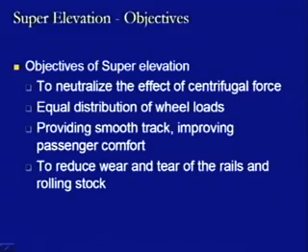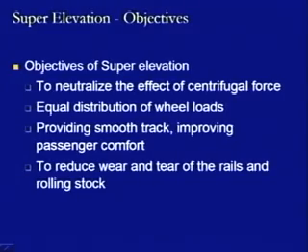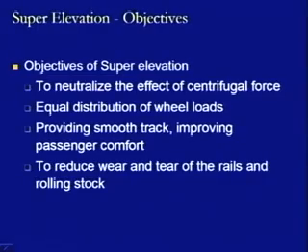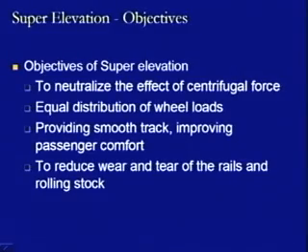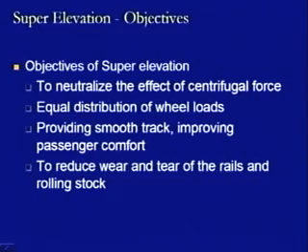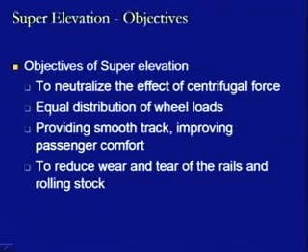Now, if the super elevation is provided, it will nullify the effect of the centrifugal force, and therefore the passenger will not feel any jerk when the rolling stock moves from a straight portion to the curved portion. So, this is another important objective for which the super elevation is provided.